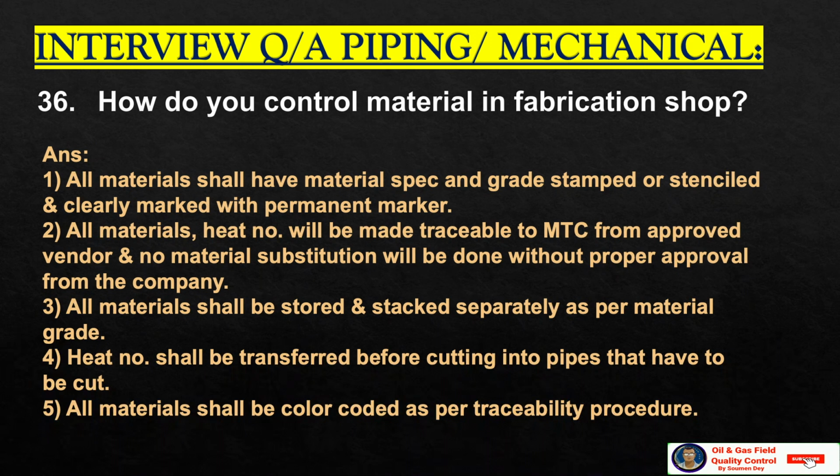All materials shall be stored and stacked separately as per material grade. Heat numbers shall be transferred before cutting into pipes that have to be cut. All materials shall be color coded as per the traceability procedure.